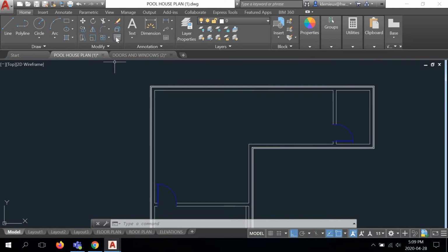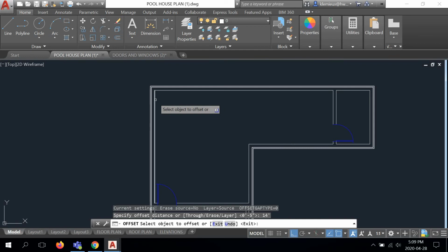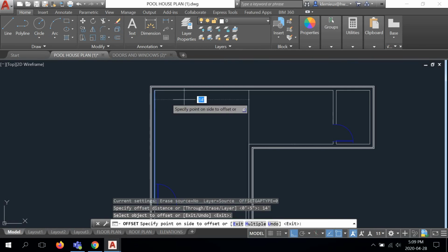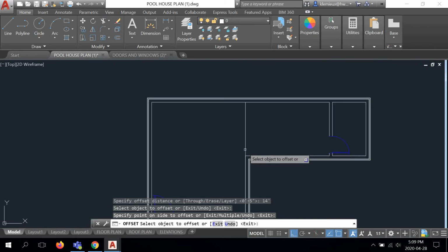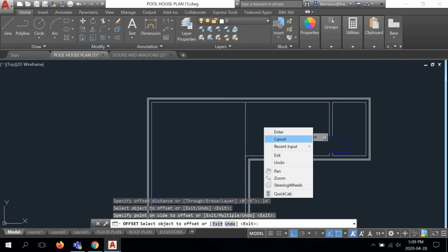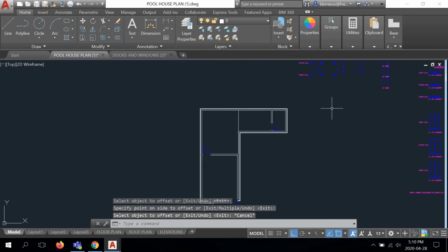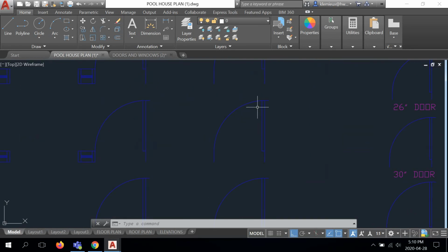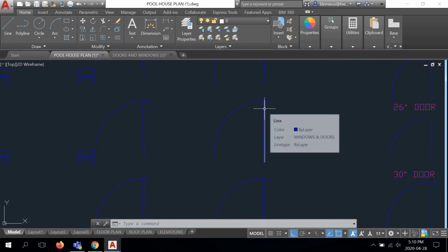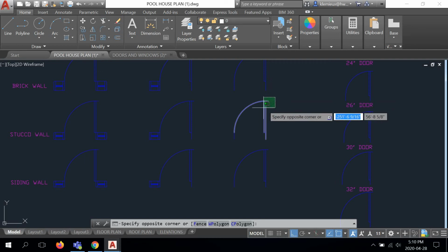So I'm going to create another offset. This time I'm going to use 14 feet. And I'm going to offset this interior finish face of the interior wall over to here, right? That kind of lands me right around where the L begins. Okay. So again, what kind of door am I going to use? You guessed it. We're going to use another stucco exterior door.